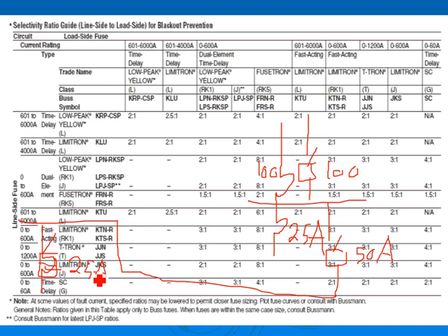So 25, depending if you use the circuit breaker, some manufacturer can go also like match this to the fuse. You can go as high as 50 if you're using the same type of fuse, QO. You can go almost up to half of this like a fuse, and you still have an acceptable coordination. So in a 100 amp panel, you can have a 50 amp fuse and have an acceptable coordination. Rule of thumb. Otherwise, in an engineering project, guys, what we do is we pull all this data about the fuses, we coordinate them, and we do the best that we can do. On the 85%, you're almost guaranteed to if you keep these ratios.